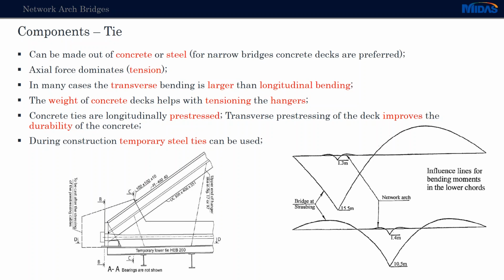And another advantage of using concrete decks would be that because of the weight of the concrete, these help with tensioning the hangers, so we have less relaxation. Also, as mentioned before, these are pre-stressed, so the pre-stress will very likely improve the durability of the concrete.